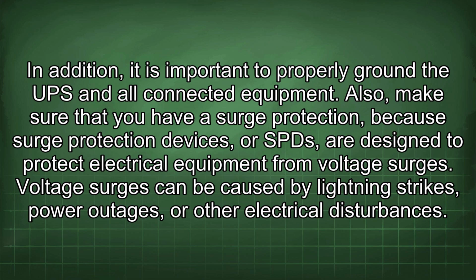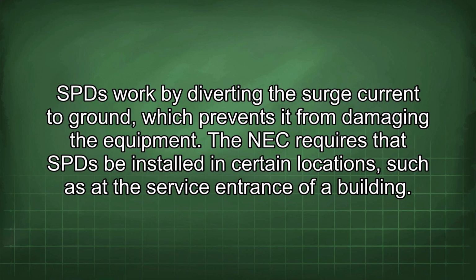Also, make sure that you have surge protection, because surge protection devices, or SPDs, are designed to protect electrical equipment from voltage surges. Voltage surges can be caused by lightning strikes, power outages, or other electrical disturbances. SPDs work by diverting the surge current to ground, which prevents it from damaging the equipment. The NEC requires that SPDs be installed in certain locations, such as at the service entrance of a building.